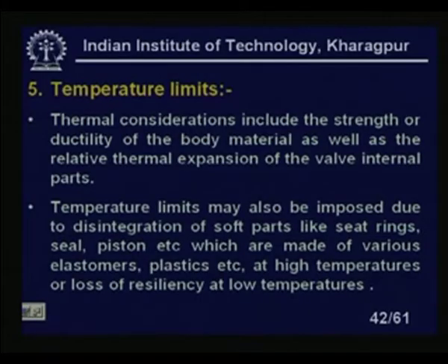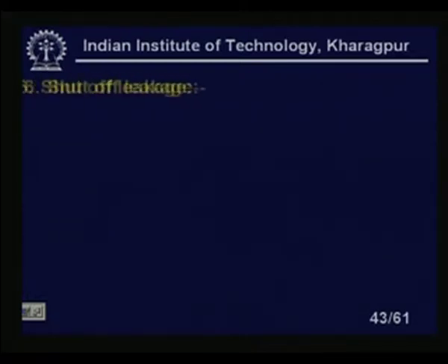Temperature limits may also be imposed due to disintegration of the soft parts like seat rings, seals, pistons, etc., which are made of various elastomers, plastics, etc., at high temperatures, or loss of resiliency at low temperatures. This is also important.